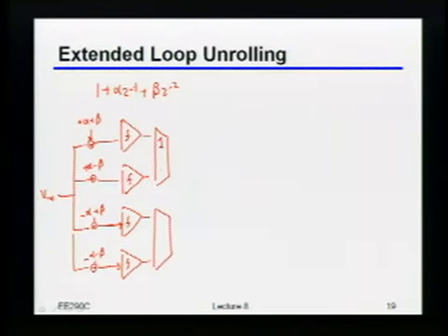As an example, based on the bit that's going to be 2 periods ago, I'm going to select, for both of these, whether I choose the upper comparator or the lower comparator. So in other words, if the bit that was 2 bits ago was a 1, then I have a plus beta, I have a plus beta.